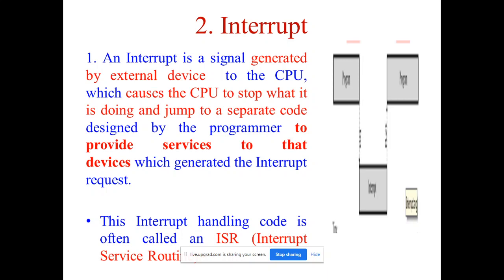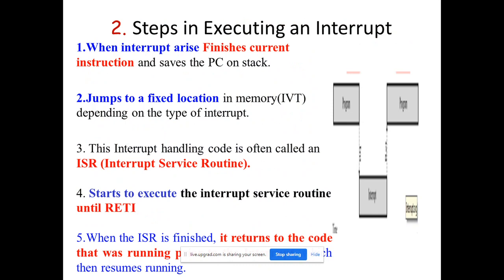Okay, then we will proceed to the next. Now, the steps for execution of the interrupt. First, when an interrupt arises, finish the current instruction and save the PC on the stack.